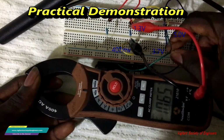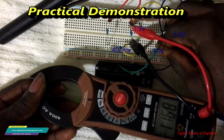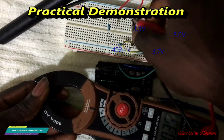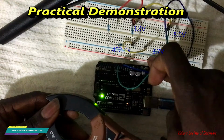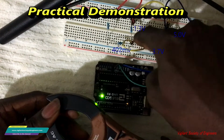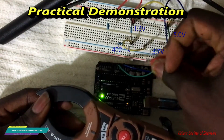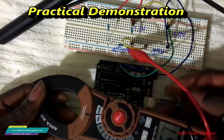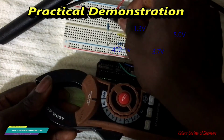All right, remember we calculated it as 1.3, right, or somewhat 1.29 around there. All right, so again the voltage drop here is the difference between the supply voltage and the one in series. So that would have given us 1.3, and as we measured within this actual circuit it is 1.1, 1.14. All right, so then let's measure across the two resistors that are in series and parallel against the 100 ohms resistor.